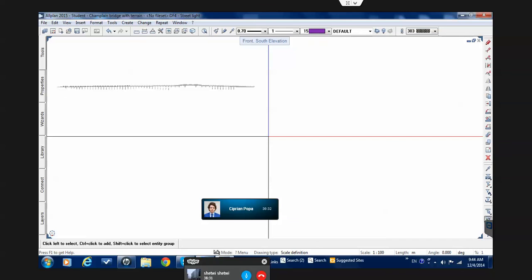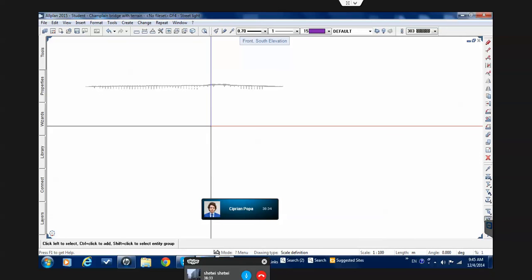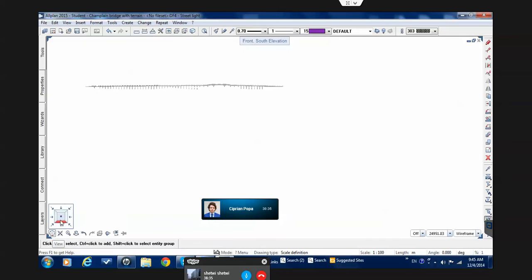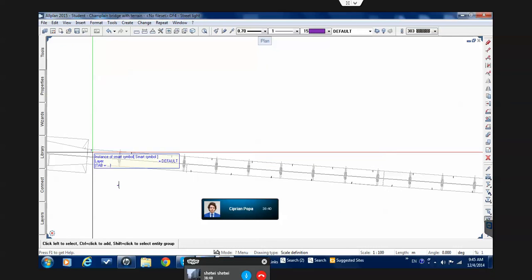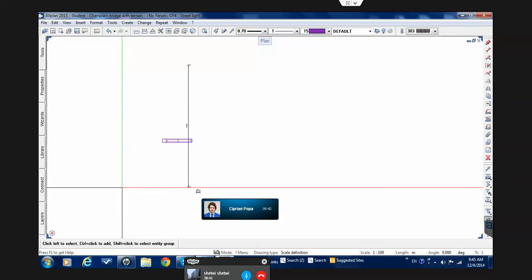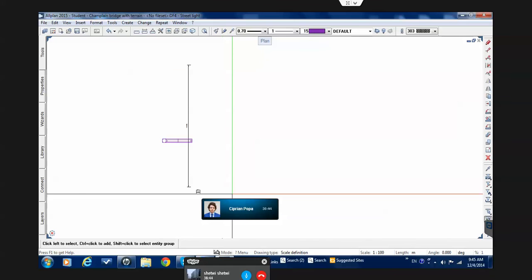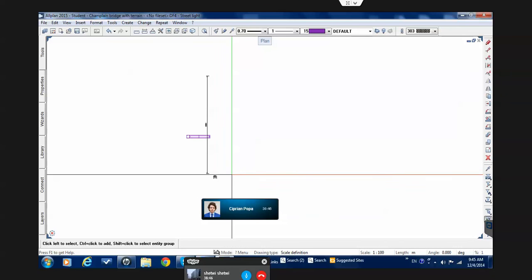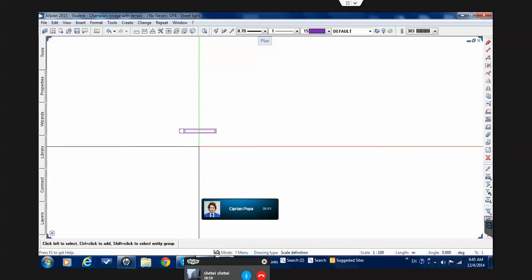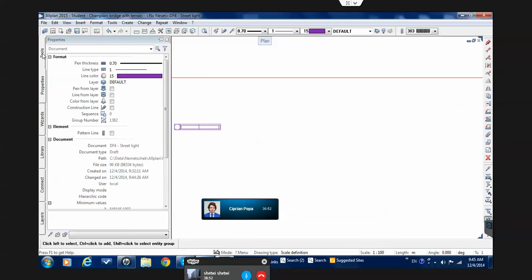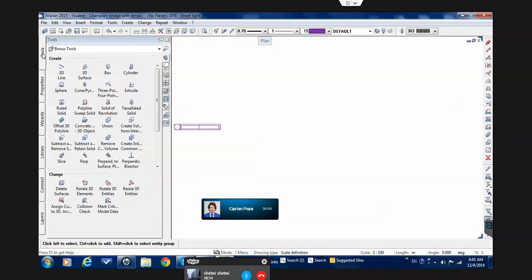And now the most important thing after we finished modeling one element, which is going to be copied multiple times. So model this lamppost, which we are going to copy many times. The essential part will be to make it a smart symbol, so no matter how many poles I have, the program won't consume more space.